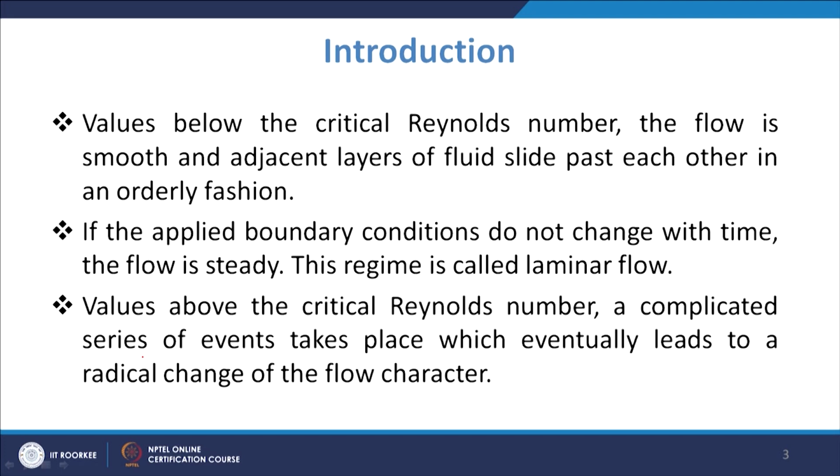So, that is the trait of laminar flow: your flow will be smooth and your adjacent layers will be sliding one above the other. They will not be mixing across in a cross-wise manner. There may be some diffusion of atoms taking place from the bottom layer to the top layer or top layer to the bottom layer.